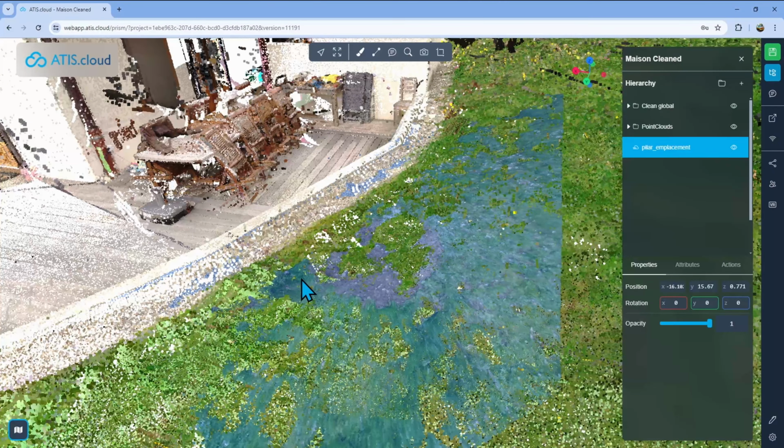So I have the distance between each leg of the cable, and then right here I'll have the total distance of the cable. So here I have 29.14 meters to be able to connect all of these panels. So basically it goes up here, goes all the way around these panels so I can connect them all, then it goes down there to be able to connect this one, and then it goes back up all the way out here so I can connect that one as well. And so with that cable distance, I can plug every single panel. I'll take 3 extra meters and it will be enough to connect all of the west panels.